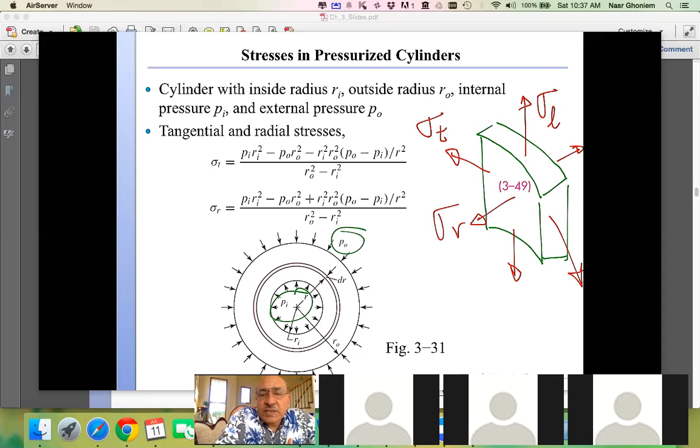And what is the story about the pressure vessel? The story is that we want, given pressure or dimensions or combinations, to find these three components of the stress and determine failure. Determine failure, meaning find the maximum shear stress or the maximum principal stress. So here we have the tangential stress equation, the radial stress equation, and we can find the longitudinal stress knowing the constraint on the axial condition.